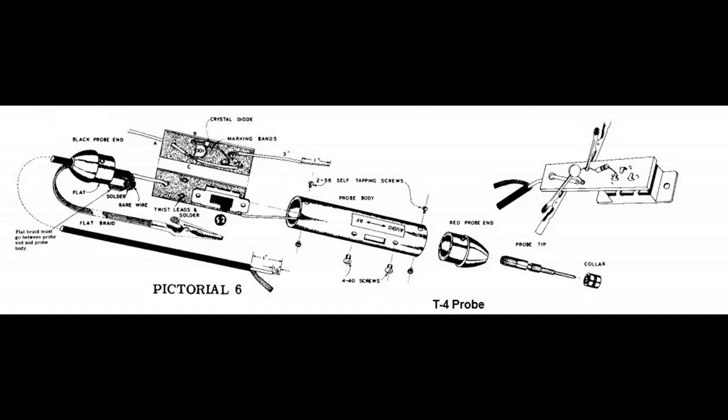So I got to thinking, you look at any of the old signal tracers, the Heathkit, the ICO, any of them, they all come with test leads, or test probes. And usually with the switch on them, they go between RF and AF and stuff like that, but always with a probe. And now I see why. By putting the RF demodulation circuit up in the probe end, all you're taking down the coax is the audio signal, which isn't affected at all by the capacitance.